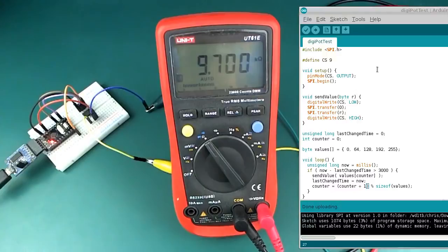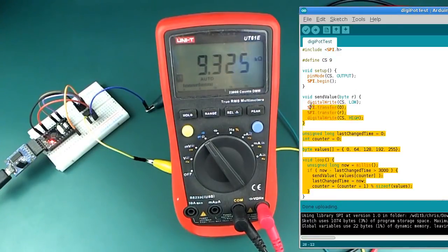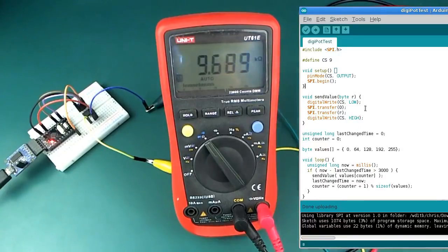Okay, I have everything connected up there, and I'm using pin 9 as the chip select for my SPI interface, which is why I have chip select 9 defined here in my sketch. So I just have a little sketch here as a test to see that this thing is connected up and it works properly. And I won't pretend that I figured this out from the datasheet. I will instead point you to a very good video that covers this in the link in the description. Basically we just need to do an output definition for that pin, SPI begin, and I've set up a little function here that will help us to set the chip select pin low and then high afterwards when we send a value to the digital potentiometer.